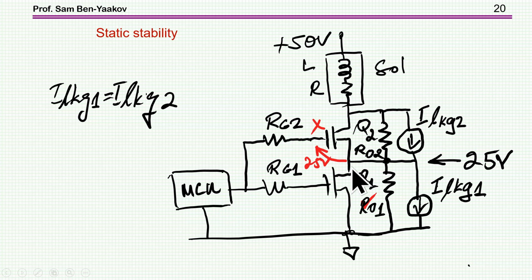This is really dangerous, because MOSFETs are usually specified to a maximum of, say, 20 volt. Anyhow, this could actually go to even 50 volt. So in any event, this is really dangerous, as there could be a breakdown between gate and source.